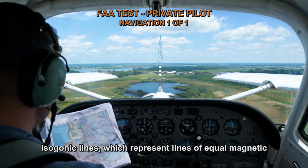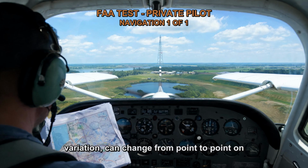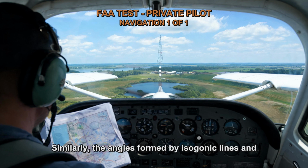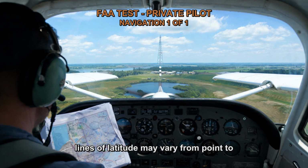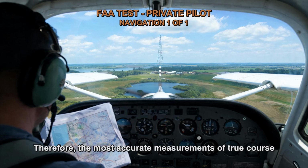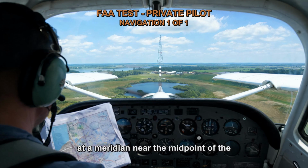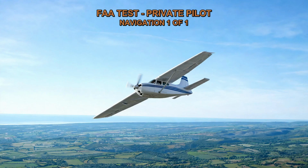Isogonic lines, which represent lines of equal magnetic variation, can change from point to point on the chart, but they are not directly relevant to the measurement of true course. Similarly, the angles formed by isogonic lines and lines of latitude may vary from point to point, but they are not the primary factor to consider when measuring true course. Therefore, the most accurate measurements of true course on a sectional aeronautical chart should be made at a meridian near the midpoint of the course to minimize the variations caused by the convergence of lines of longitude.